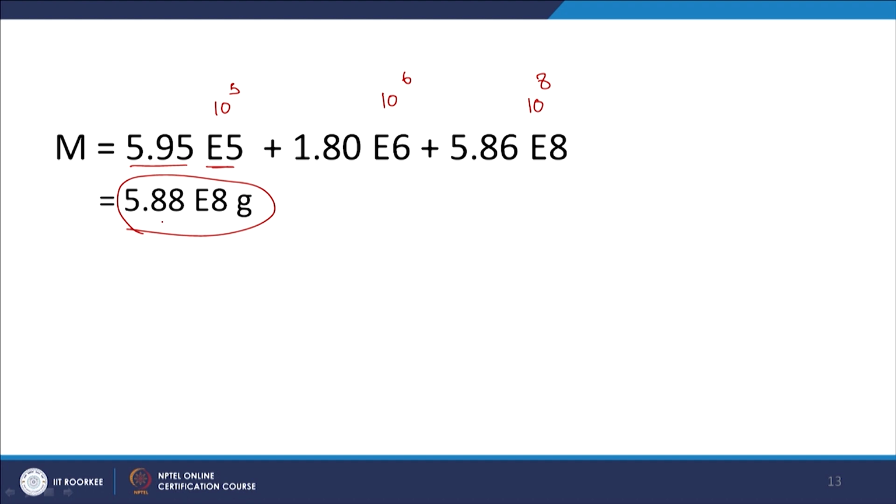We will come back to that, but the reason I write it out this way is that if I look at the fraction, what is it now? It is 1 to 10 to 1000. So, if one part of the contaminant is dissolved in the water, you have 10 parts adsorbed onto the soil and 1000 parts present as the NAPL. Again, NAPL was only present as 1% of that particular pore space. So, you should understand the criticality, or complexity, of having NAPL present in your contaminated site.